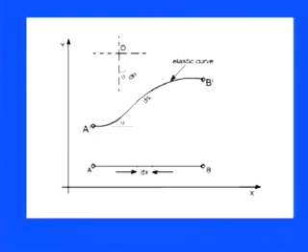So always make a clear difference between ds and dx, because the slope will come for dx, there is no slope here. But if the slope is very, very small, as we are generally assuming, since these theories are applicable for a small deflection curve, then for that kind of section ds is almost equal to dx.